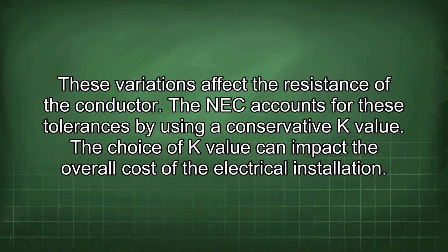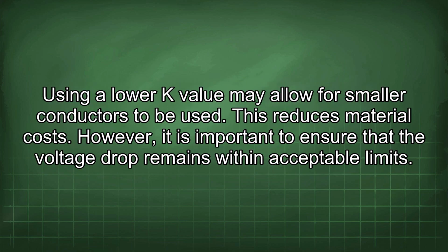The choice of K value can impact the overall cost of the electrical installation. Using a lower K value may allow for smaller conductors to be used. This reduces material costs. However, it is important to ensure that the voltage drop remains within acceptable limits.